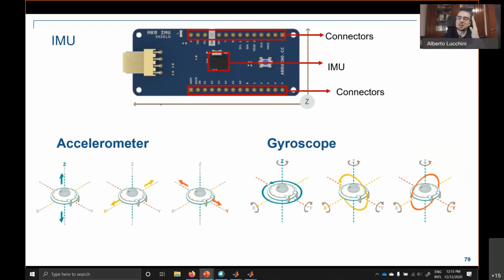When we start the experiment and the motor starts falling to one side or the other, the gyroscope will provide information about the angles and also the derivatives, so the speed of the falling. With this information, we will be able to control the system. So it's the sensor in charge of acquiring the information about the position of the system.